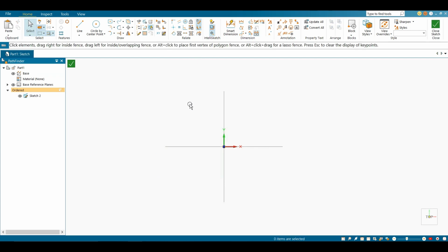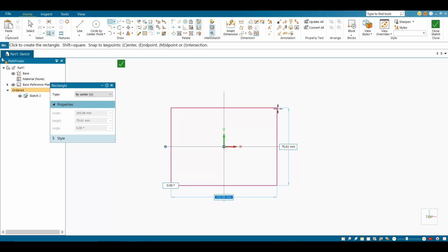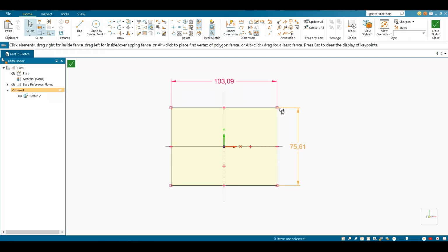If you want a detailed video on what a constraint is, you can comment, and I will cover that. In Solid Edge, if you create a sketch and provide dimensions, like here I am providing its two original dimensions to define it, you can see that the color of the sketch changes to black. It is because in settings I have set that if the sketch is fully defined, it should convert into black color. You can change that setting also.